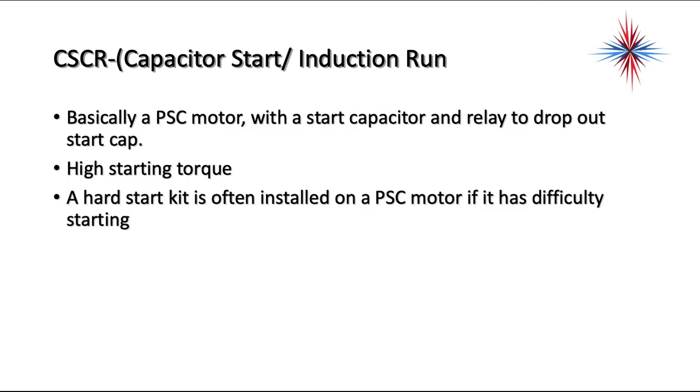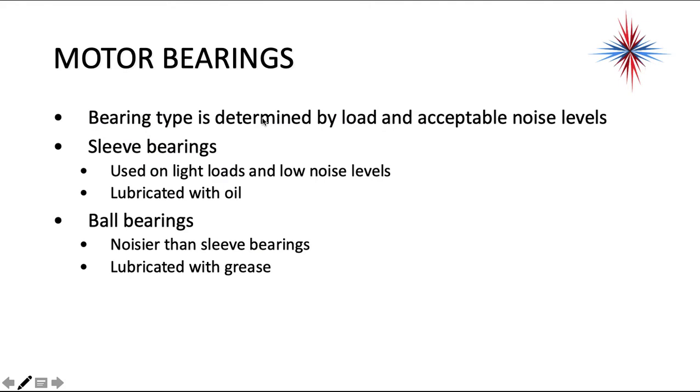Okay, high starting torque, hard start kit, and this up here should be capacitor run. A hard start kit is often installed on a PSC motor, and if we take a look at the wiring diagrams, and I'll show you that in a minute, you will see that.